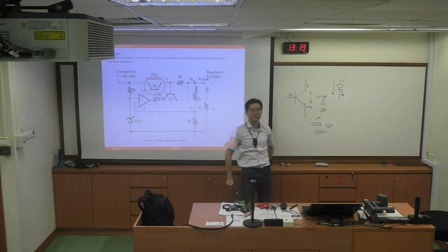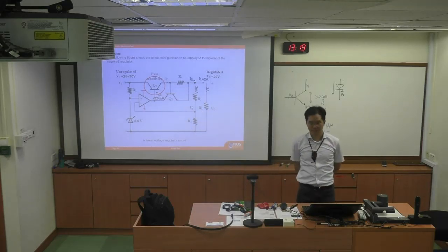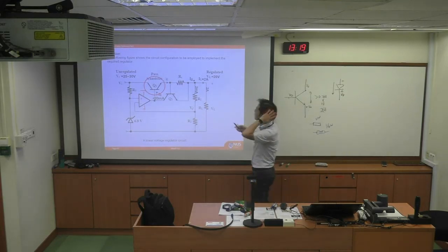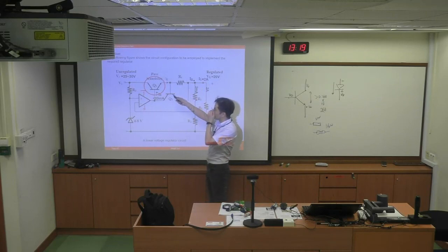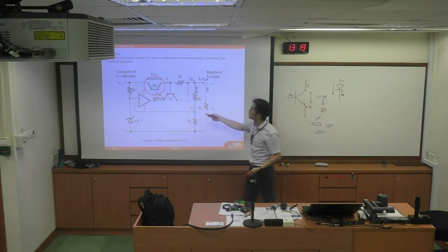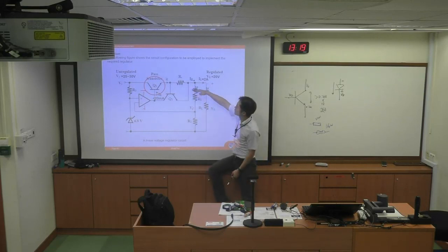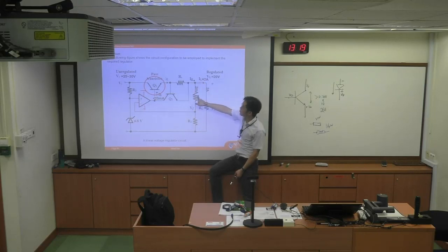Yes. So if I wanted to change the voltage and maybe drop it to 10 volt? Yes, of course, you have to change it, because as you can see, everything changes from the sampling network R1 and R2. So if you want to drop it, you probably want to control the R1 value so that the resulting Vref is still 6.8 at the lower load voltage, yes.